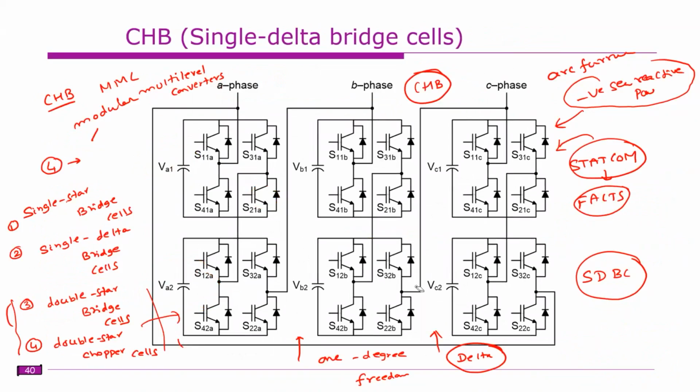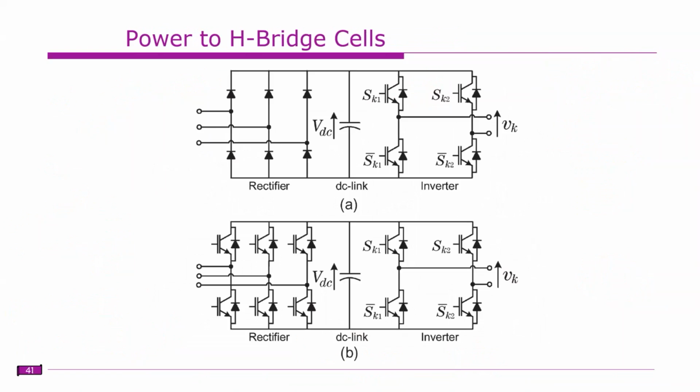So this is about the selection of cascade number and choosing the DC voltage based on the voltage requirement. Generally the cascade number depends on the number of available switches, and if we choose a larger value of cascade number, the size will increase. So somehow we need to optimize this. The next thing is how to power these H bridges. As we already discussed, these H bridges are isolated, so there is no physical connection between these H bridges